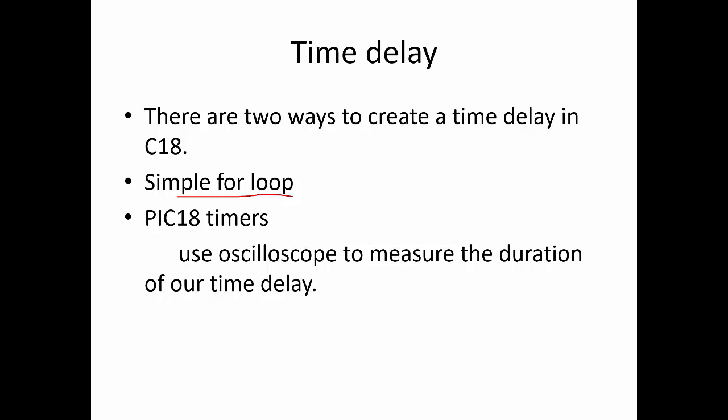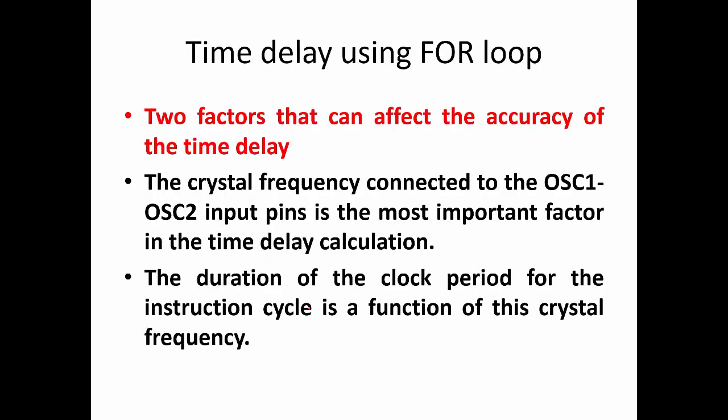Likewise, we have to apply some trial and error loop concept, and measure it using an oscilloscope. Another option is PIC18 timers. So we use an oscilloscope to measure the duration of our time delay.